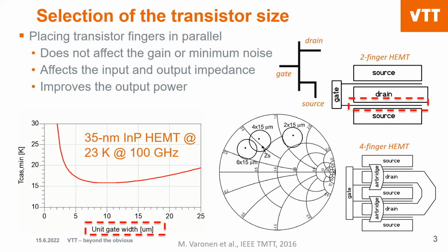And this doesn't change if you embed your transistor with any kind of a lossless matching network, feedback, whatever you add around it. That doesn't affect this number. It will affect the number that usually is used at lower frequencies, which is the minimum noise figure of the transistor.